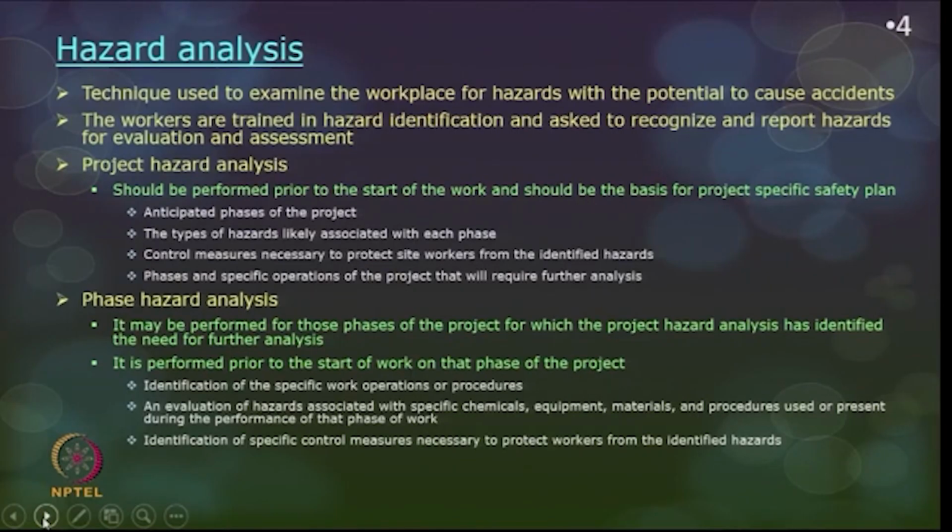There you have to go through 4 different steps, and those 4 different steps will help you to identify and think of how to manage the hazards. So, hazard analysis is a technique used to examine the workplace for hazards with the potential to cause accidents. The workers are trained in hazard identification and asked to recognize and report the hazards for evaluation and assessment. So, project hazard analysis should be performed prior to the start of the work.